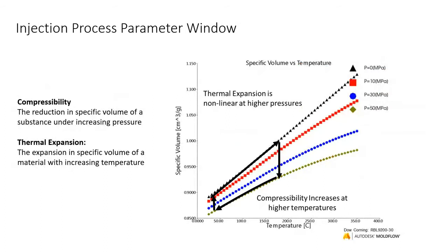And then in terms of rubber, it's not as simple as just filling a known volume. The compressibility factors and the thermal expansion factors, because things are changing in temperature, are very important. And so we have to take the understanding, in this case, the cure temperature with respect to the specific volume or the density of the material. And we note that in typical molding processes, there's a cycle that occurs.